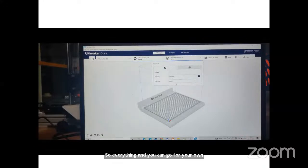Now talking about the print cores, you can use different types of print cores, which differ by their nozzle diameter. You can see AA 0.25, AA 0.4, AA 0.8, BB 0.4. So basically AA 0.25 means the extrusion diameter of that nozzle, where the filament comes out, is 0.25, and 0.4 means the diameter of that nozzle is 0.4.